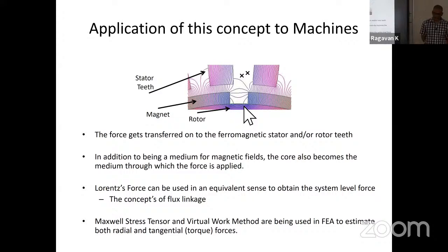When you add ferromagnetic material, you are helping the magnetic field sources present inside the machine to give out their magnetic field to a greater extent. If you don't do that, there will still be field coming out of these magnetic field sources, but it is not high enough. So whenever you see these slotless machines, they're high speed machines where the magnet's B is less.